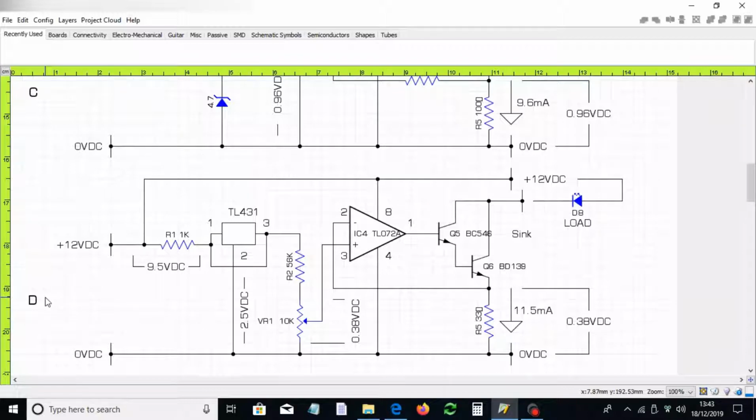Okay, moving on to my chosen device. It's the TL431. Again, I'll include a link below to the data sheet regarding this device. It's very economic. You can pick them up for pennies, and they're actually quite good. I didn't particularly worry about the output. It's 2.5 volts. It does vary from device to device and depends on what category of device you order or obtain. That voltage can always be trimmed out in R2 to the exact voltage required.